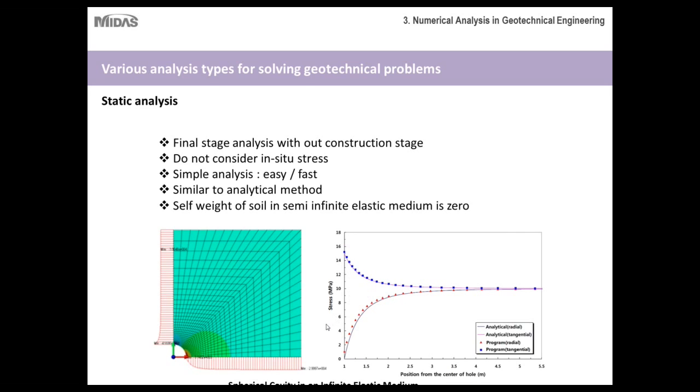So since static analysis is fairly simple to run, it's always good to have your results checked against each other. In other words, if you have your numerical analysis and you get a certain set of results, it's good practice, or a good rule of thumb, to run your analytical analysis to make sure that your results are along the same lines. As you can see, this would be passing because the analytical and the numerical modeling results are roughly along the same lines. There isn't too much separation between the 2.